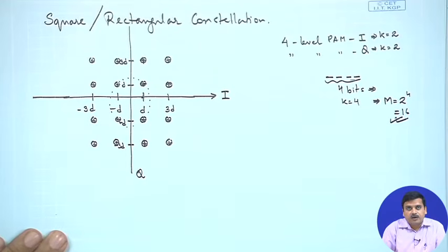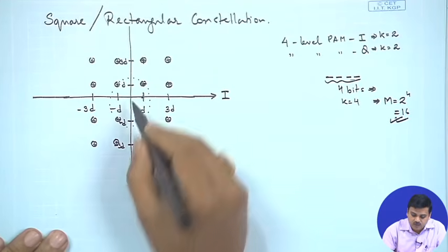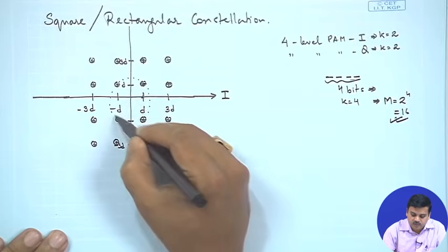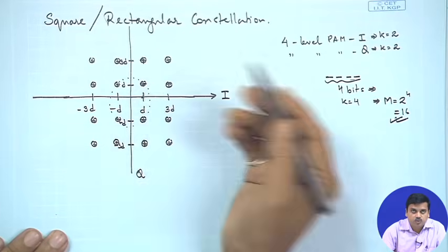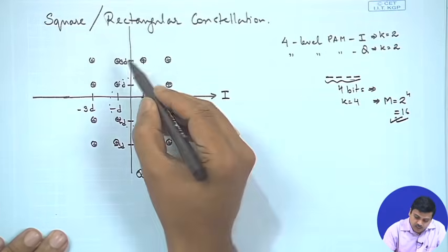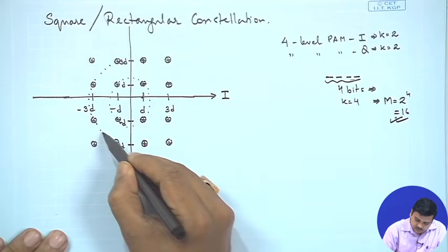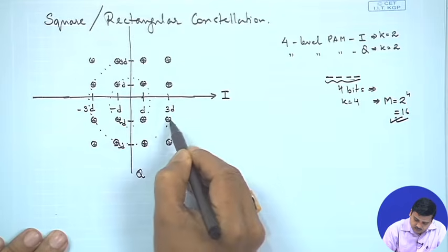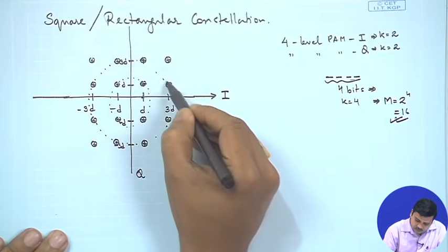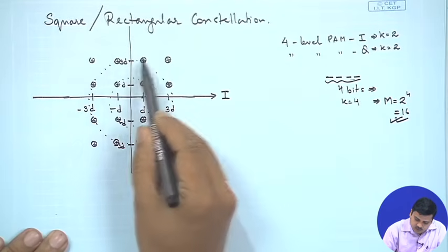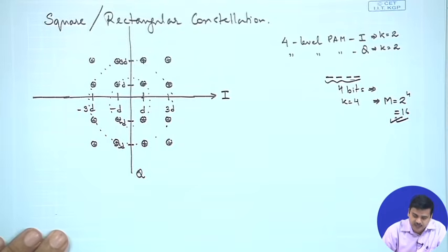This is a phase shift keying with one level of amplitude. So, there are 4 possibilities, that means 2 bits. And if I select these, we have 1, 2, 3, 4, 5, 6, 7, 8. So, we have 8 possibilities, so 3 bits.